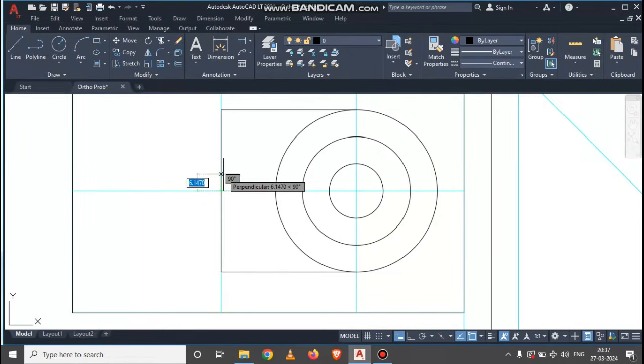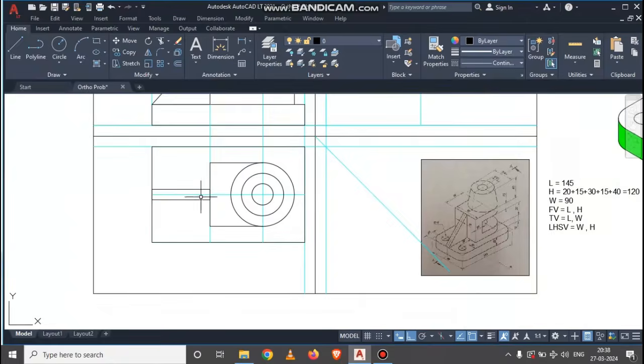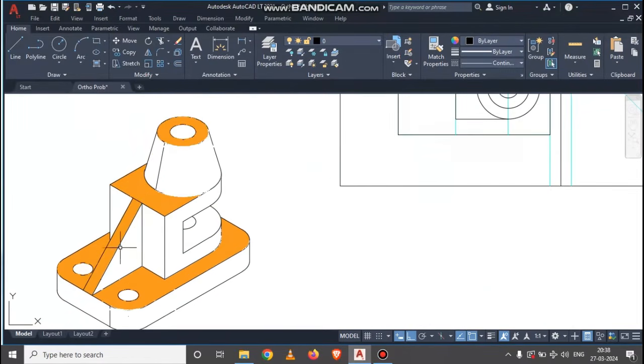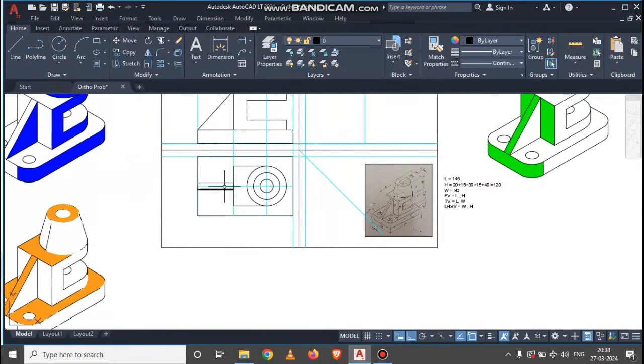From this point we have to take vertical distance 5 mm. Again we have to draw the horizontal line. So to have that exact horizontal line, turn on this ortho mode command, just click over here. Again from that point enter 10 mm and just move horizontally to get this point and just end over there. So this rectangle is nothing but this portion, okay, this inclined portion in a top view portion, okay. So this is nothing but the rectangle for the rib that we have over there.